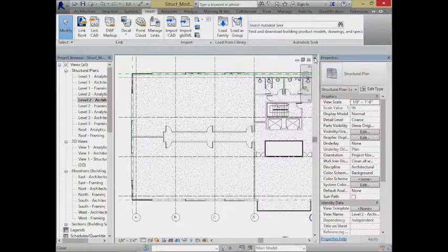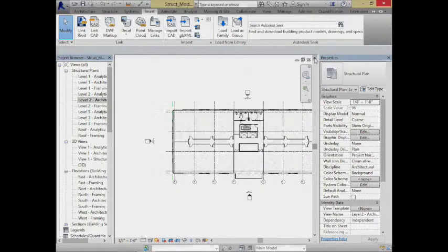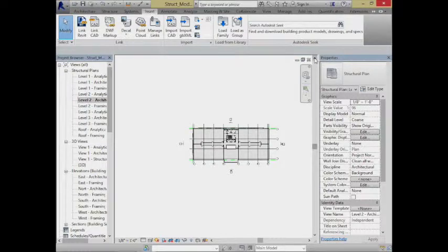But it all starts with this notion of, can we come up with good grid locations? Because you're just looking for locations where it'll make sense to break up the structure into some pseudo-regular grid that'll support everything without having the spans get to be too great. Because the bigger the spans are, the more these beams are going to take up room within this space, and it's going to get harder and harder for the non-structural people to work together. So that's one of those trade-offs. The grid locations and the spans will end up determining a lot about the heights of the beams, which will then make other people's lives harder to work with. Okay, so we'll start with just this notion of the grids.